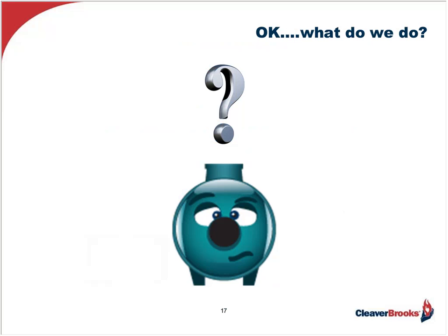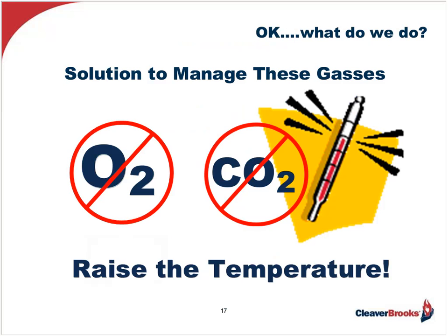Okay, so how is it accomplished? Very simply, applying heat in the proper way. Remember I showed you a slide before which indicated the role heat plays in changing chemical formulations, resulting in free carbon dioxide combining with water to form carbonic acid? It all started with carbonates of alkalinity in the feed water. Well, this CO2 can be totally removed from the system by applying heat in conjunction with another factor, which I'll discuss in just a minute.